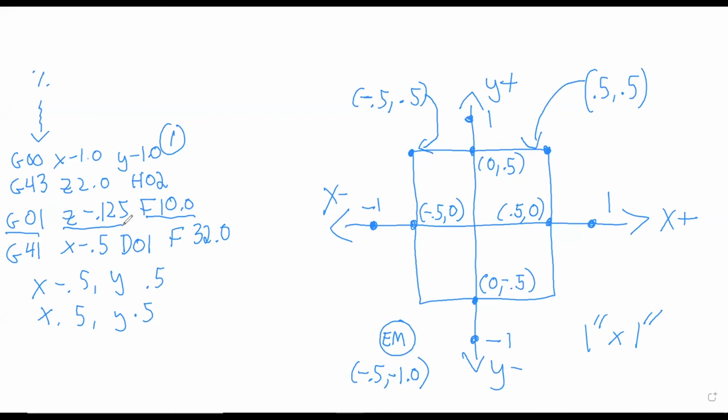So we move from this location, the G00, and we want to turn on cutter compensation left. We do that with a line movement, which is still modal, and we call out a D value to reference the diameter in our tool geometry. And then we move to the X -0.5. That is at least half the cutter diameter. Right? If we're using a 1/2 inch end mill, half of the cutter diameter is 0.25, so we are moving actually 0.5. So we have enough room to turn cutter compensation on.